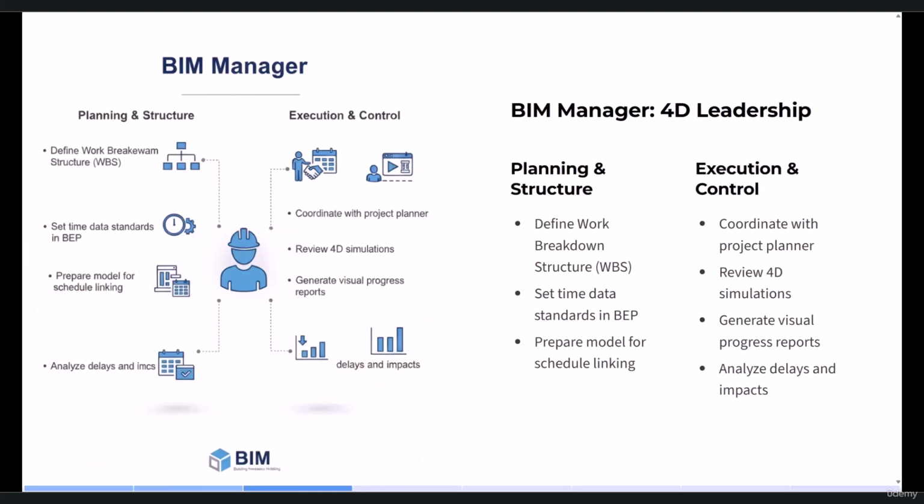So when we go through every story, we have to do some execution activities. The first one will be excavation and preparing the site, and after that we'll go for the foundation. After that we'll go for the structure, and the structure has a lot of items like columns, slabs, beams, and other ones. After the structure, we'll go for walls, mechanical systems, and after that, we'll go for finishing works such as plastering, tiling, and wall painting. So in fact, the project will be divided into different parts so that we can have a really good schedule for it.